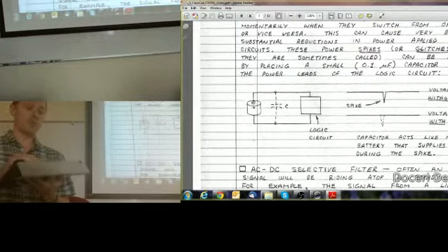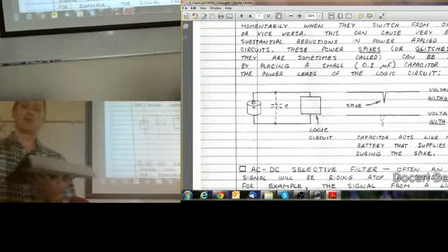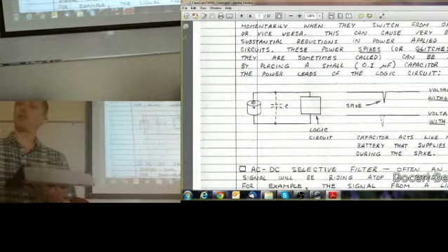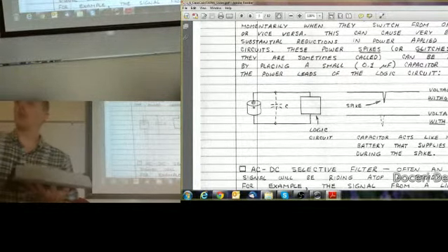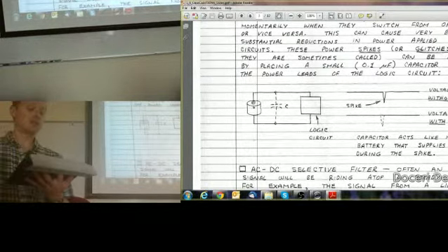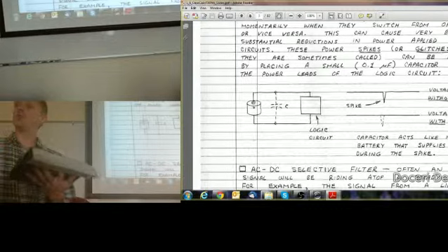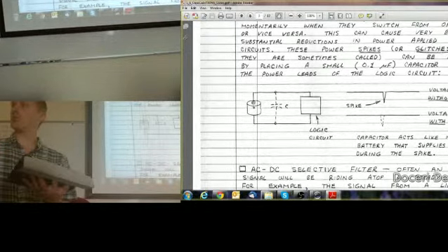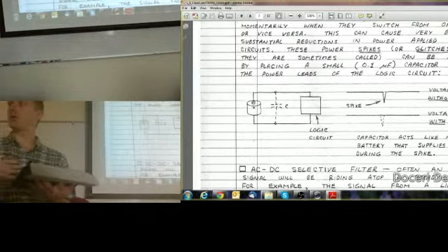Now the capacitor, for changing signals, has a very, very low internal impedance. In fact, the internal impedance is going to be equivalent to its ESR, equivalent series resistance. So that's why ceramic capacitors are used a lot for decoupling, because they have a very low ESR.